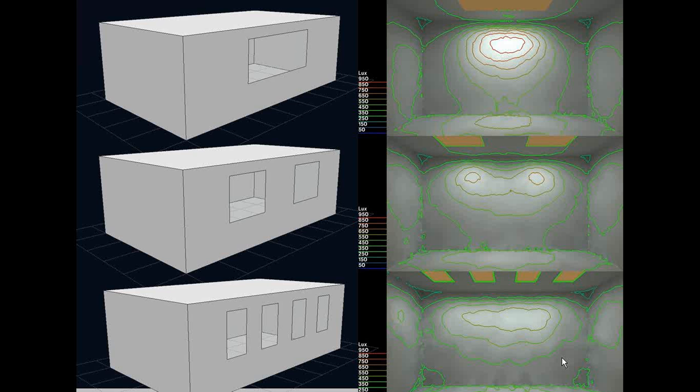Adding an overhang makes sense because you get direct sun hitting the overhang and then getting reflected deep into the office space. Whereas on the north side, adding an overhang actually blocks the diffuse light, so it was not useful. This kind of input the architect can generally use in trying to optimize the design.